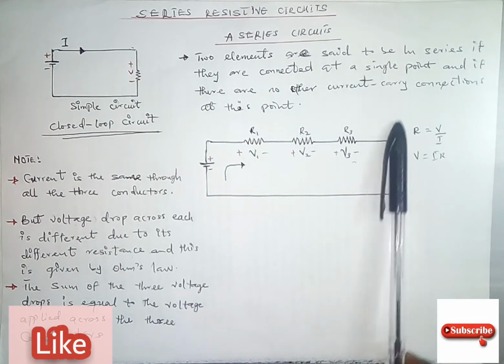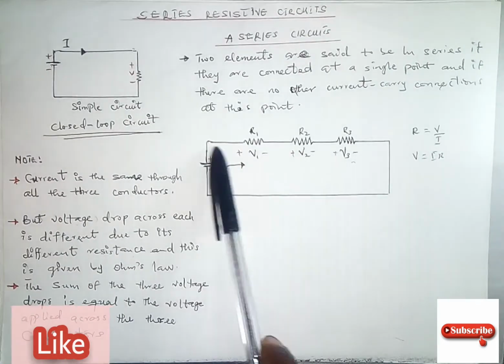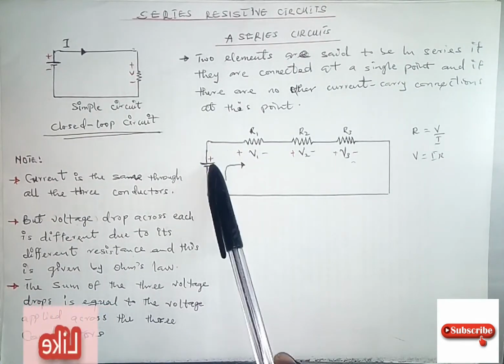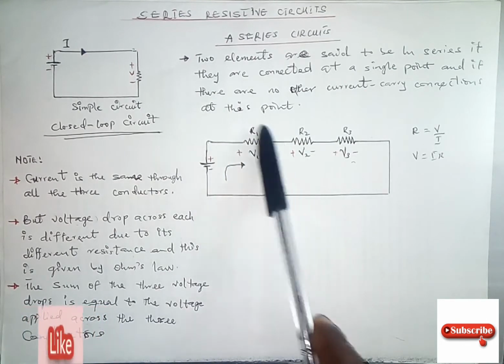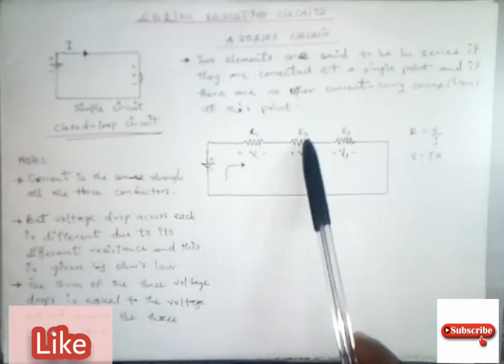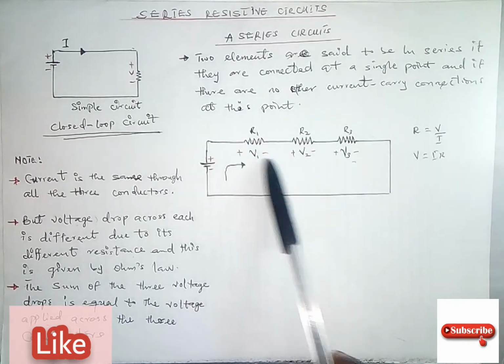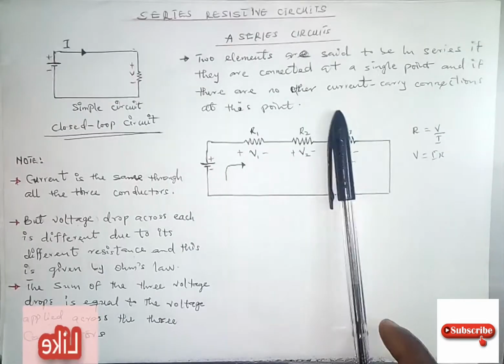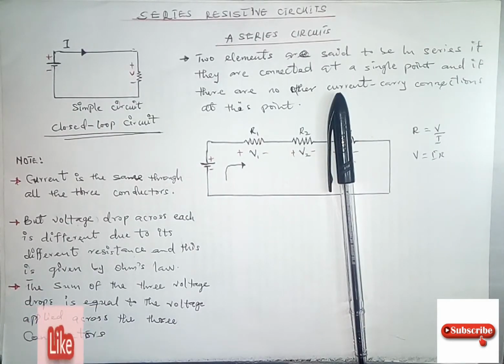Which means the voltage that rises from this point is, no matter what, going to be equivalent to the sum of all the voltage that drops across these components. So that is what the last one is all about. So now,